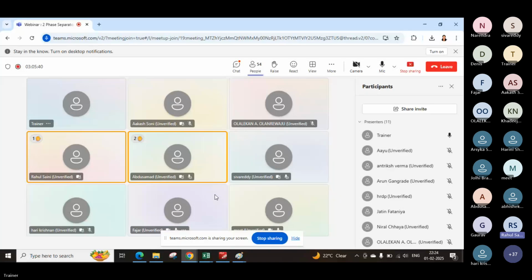Yeah, actually the alarms that we have considered, the standard that we're considering, will remain the same for all the applications. You consider the bottom length below the inlet nozzle that we have considered, it will almost never be changed for any flow rate, while the diameter will change. So in this way, if we consider this reference, the height of a vertical separator will remain the same, irrespective of the diameter.